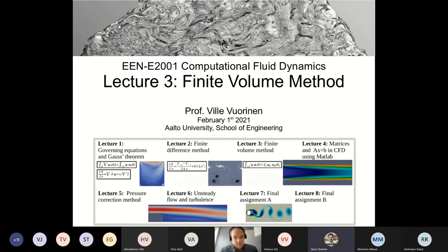All right. Yeah. Thanks. You can solve fluid mechanical problems, especially laminar flows, with COMSOL or Elmer or some other codes. But usually these finite elements work best for laminar flows. When you go to turbulence or anything a bit more complex, you have great benefits and advantages in the finite volume method.